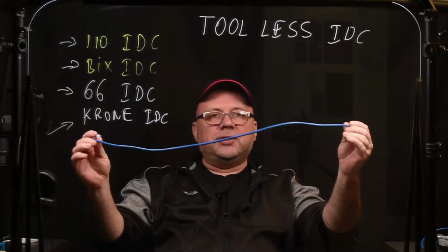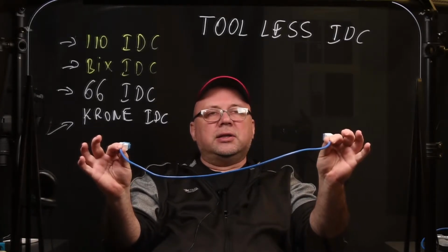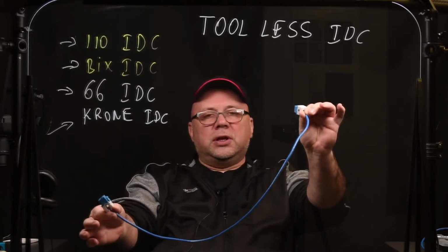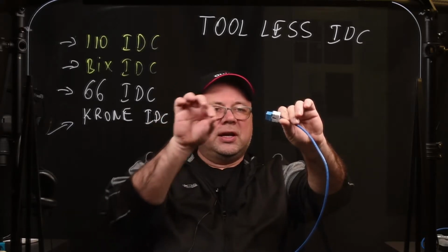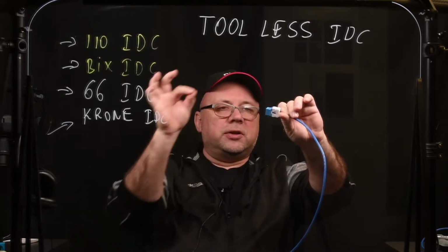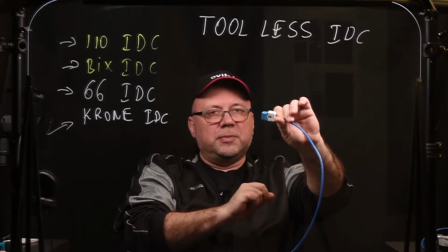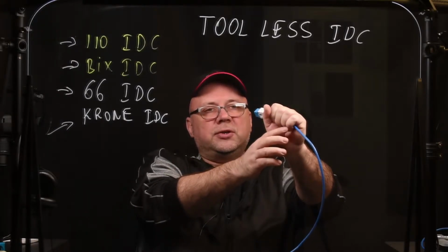So that is basically set in stone. It's just done. Once it's terminated, nobody touches that. If you want to connect equipment, you use patch cables from the patch panel into whatever the equipment is in the equipment rack location. But you're not playing with the permanent installation.